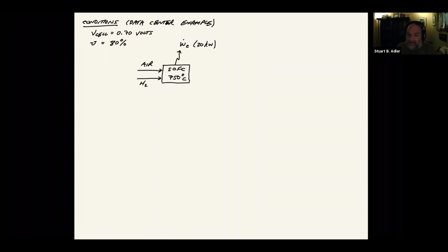When we say we're operating at 750C, what you might imagine is that as gases go through, they're going to come to some type of thermal equilibrium with the solid surfaces that they're in contact with. And that's generally the case. So as this thing's operating at 750, we've got all this radiative heat transfer going on. And by the time the gases leave, they're leaving more or less in thermal equilibrium with the solid surfaces that they might come in contact with. So these gases are coming out at 750C, hydrogen, H2O.